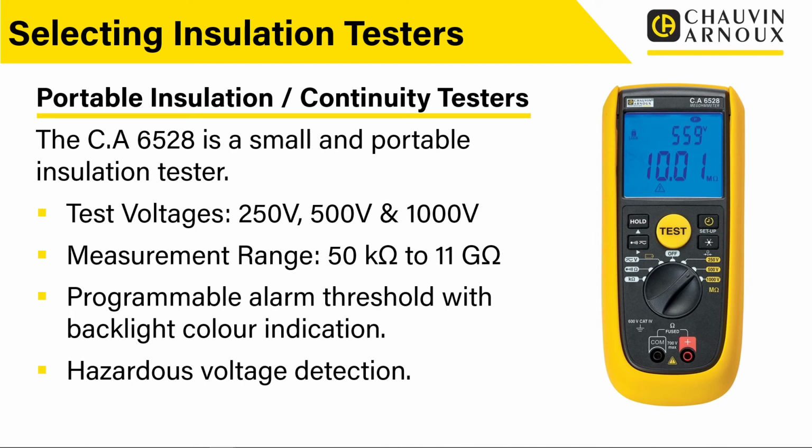It actually tells you that the insulation has got a problem. It's also quite useful if you're testing a piece of equipment, maybe you're leaving it connected up to the instrument and you're doing some alterations, or you're wiggling some cables or something like that in a piece of equipment, and then you'll get that indication. So the alarm function is quite good on that.